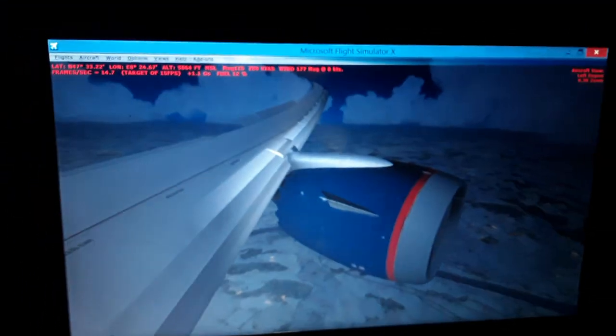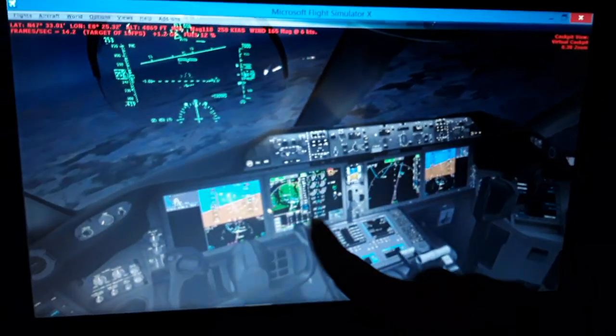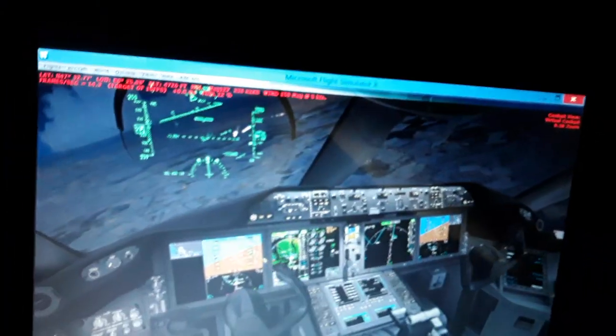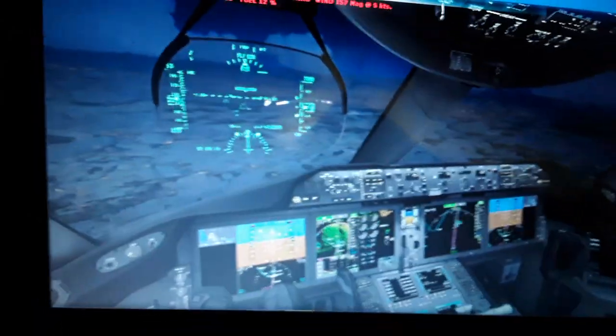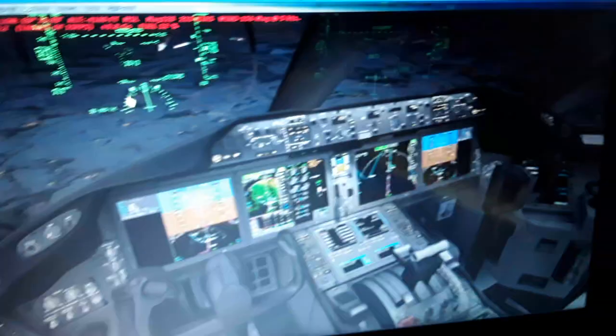So we have the correct flight path right now. Use the rudder pedals over here and the ailerons to align the airplane like this, as you can see, as we are descending for landing. So we have the runway over here. We have the LSZH localizer also. We can align the horizontal localizer and the vertical glide slope, the angle of approach.